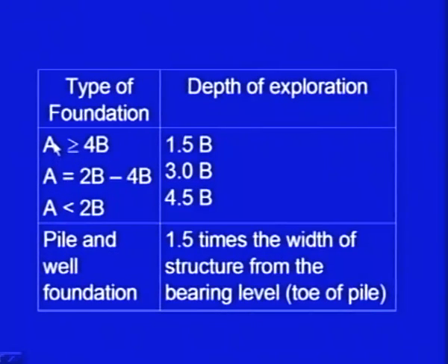If the clear spacing is more than 4B, the minimum depth of exploration is 1.5B. If it is between 2B and 4B, the minimum depth of exploration is 3B. If A is less than 2B, the depth of exploration is 4.5B. Again, please remember, these are only guidelines.